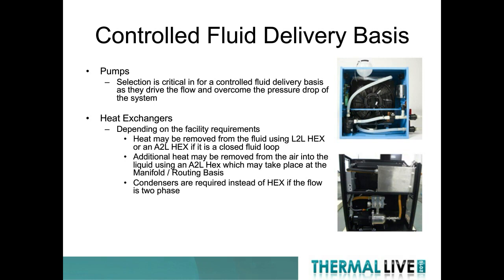The final basis we're going to talk about is the controlled fluid delivery basis. So this is where we use pumps and heat exchangers. This is what's driving the system. It's called a CDU, a coolant distribution unit for data centers. That's a common name for it, a CDU. But we also see them, a chiller to some extent can be a controlled fluid delivery basis. But the key elements of this are the pump and the heat exchanger.